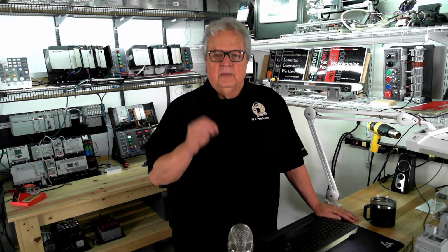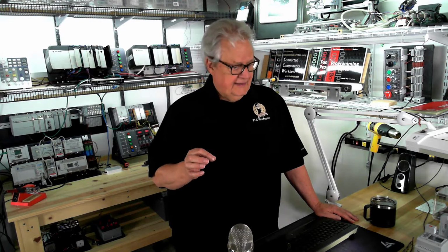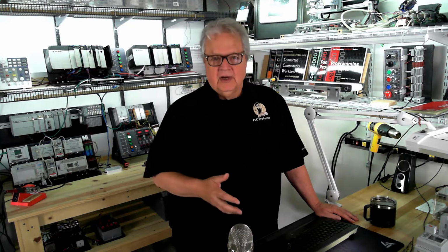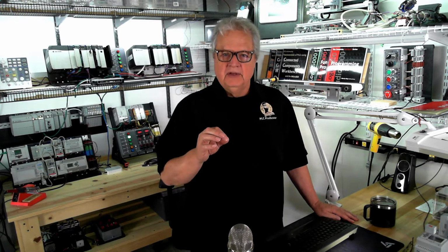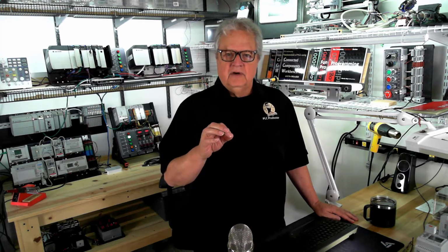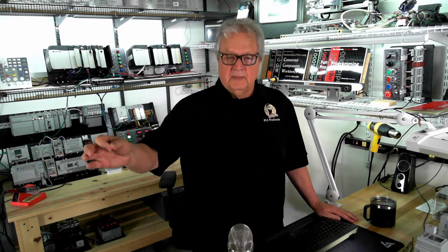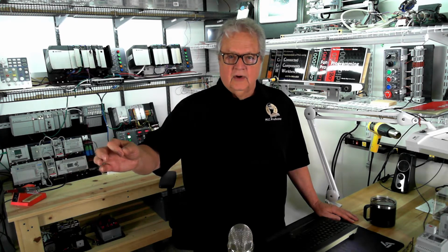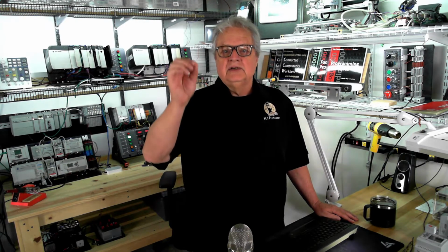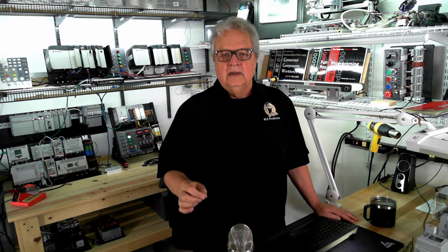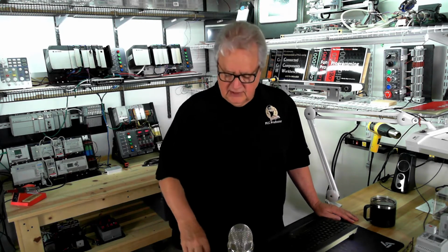Remember, we're using normally closed buttons for stop. Well, when you run the logic, you have to go turn all those on, because remember, the stop buttons are normally closed, which means they're feeding voltage to the screw terminal, so that bit memory is on that represents that input. So if you download and go to run your logic and you haven't gone in and toggled those all on, then your logic's not going to work. It's like somebody's holding down all the stop push buttons.